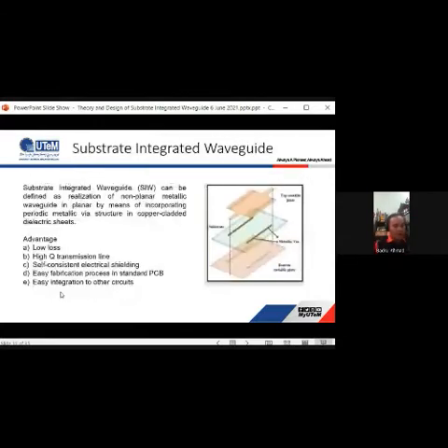So what does the substrate integrated waveguide look like? The first thing that you can see is the transition between SIW and microstrip line. It's very simple. As you can see, it just uses a microstrip taper, or the coplanar technique. What are the advantages? If you put rows of vias between the structures, it acts as a shielded structure.